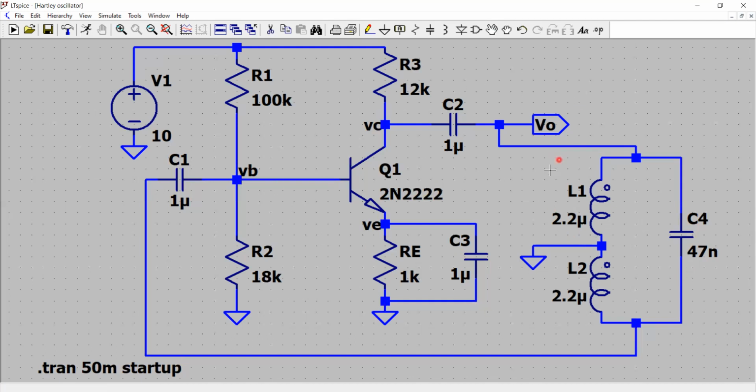It's a closed loop with the closed loop gain given by A multiplied by beta. So A is the gain of the amplifier, beta is the gain of the feedback network. This network provides the gain to the signal, that is the amplifier, and this network attenuates the signal, and that's why opposite terms are used. Here it's called gain, here it's called attenuation.